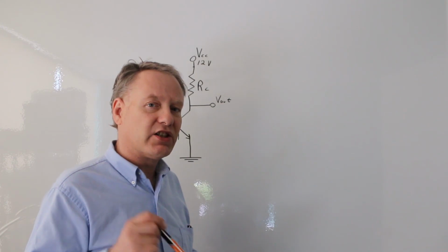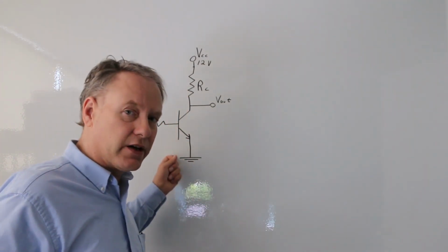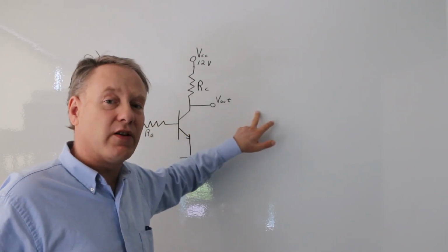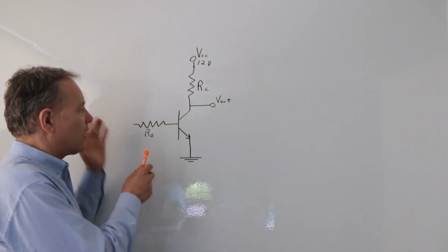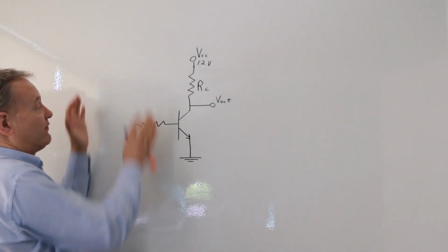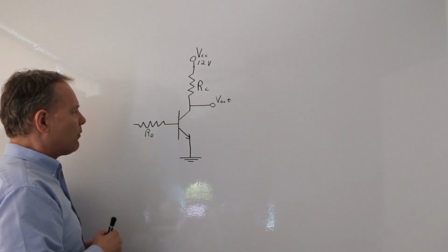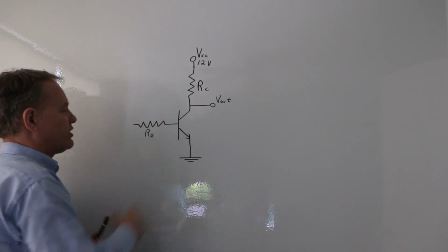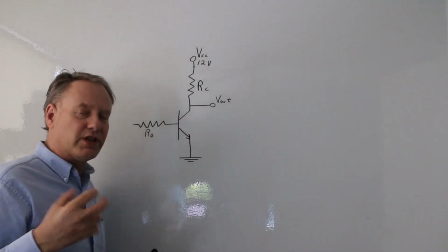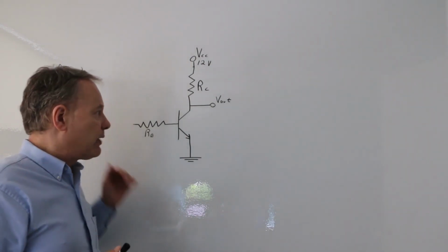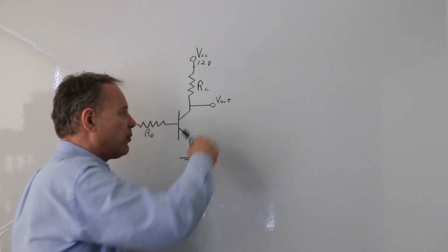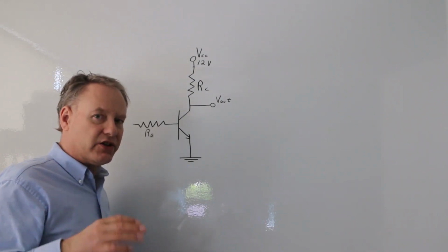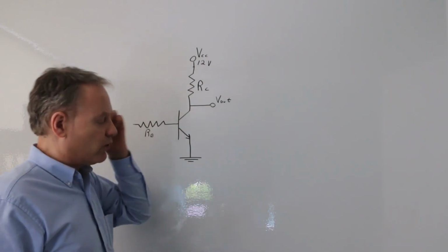So right now, let's talk about how to put a thermistor into here to actually have variable resistance, giving us a very specific voltage coming out of here. All right. So we've got this basic BJT here, and I've left this big blank here. What I want to do is align some kind of thermistor in here. I want to obviously put voltage in here, and I know that the voltage needs to change. It needs to vary because I want a varying output here. So I'm going to have an analog signal coming in that's in relation to the changing of the temperature, and then obviously the voltage coming out.